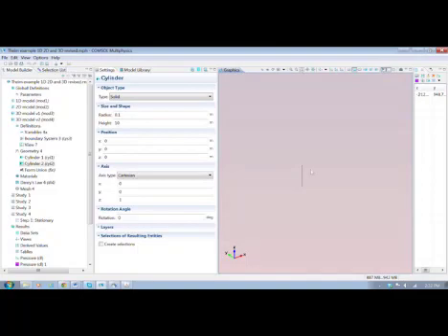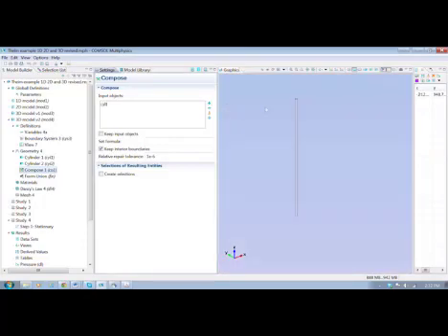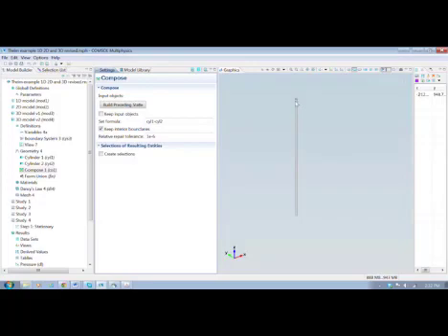So there it is. It has some finite thickness now in this case, and you can see it's an open cylinder. Well, actually, it's not an open cylinder yet. We have 2 cylinders superimposed on one another, but what we'll do is put in this thing called a Boolean Operation, and then we'll select both of these cylinders, cylinder 1 and cylinder 2, and now we can just simply write a formula that operates on these geometric entities. So we go cylinder 1 minus cylinder 2, and we run that, and what that does is cuts out the cylinder 2 material from the cylinder 1 geometry.